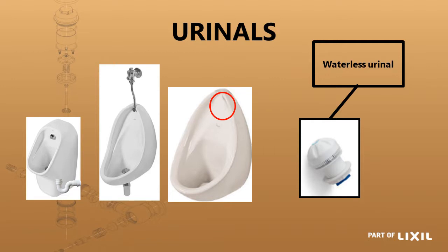and you'll see that this particular one here doesn't have a spreader, because with the waterless urinal no spreader is required. Because if we have a look at the waterless waste that is used, that has got a non-return valve in it, so any water going into the bowl and down the waste trap, you're not going to get any smell coming back up because of the non-return valve. So that can be used in all 3 of those applications, all 3 of those urinals: the sweet pea, the Lavatera, and the flatback.